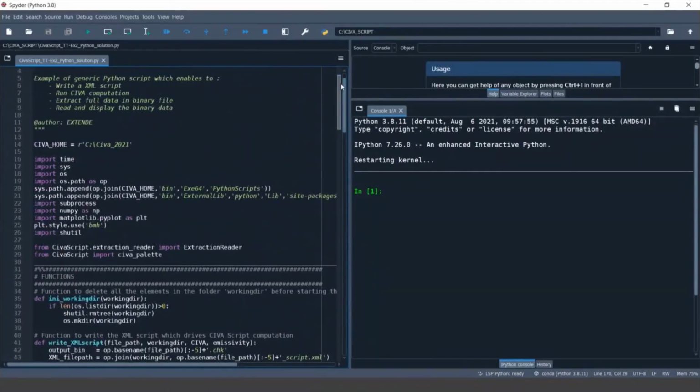You define, of course, the level of script that you want. And the idea with CIVA script is to be able to change the parameters in the CIVA simulations, to derive and launch a series of simulations, and to extract automatically the results. And thanks to the results you have extracted, also to define your own analysis process and maybe your own post-processing formulas, and all post-processing techniques can be applied by script in your Python script. Okay, so CIVA remains the simulator, but then you can drive that and maybe define several loops of modeling